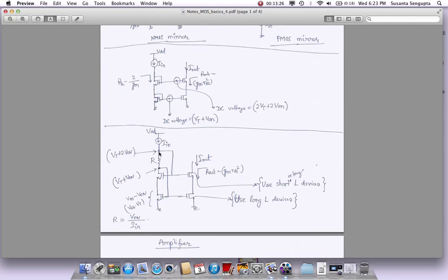So if you have 900 millivolts here, let's say VDD was 1.2 volts, yes, you can make this circuitry work in the low voltage technologies. But for high voltage technologies, we won't be able to. We don't have a problem because there you can just use this. You don't have to do all this. So this is one of the other modifications you will see, and in industry it's quite commonly used, this kind of structure to make a cascoded current source.